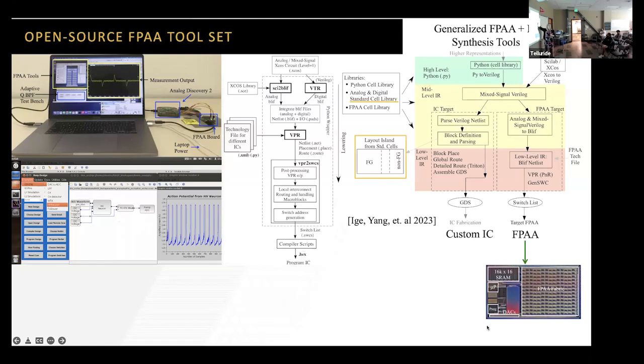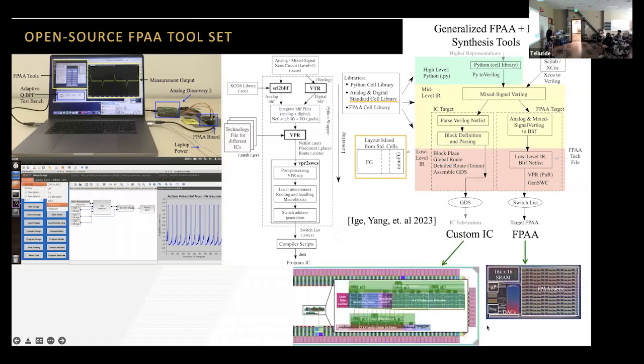You might also go, wait a minute, there's a different side to this flow that I forgot to tell you. I have a mixed signal structure from this high level. Same concept, that could go down into this side of the FPAA, but can also go here, and now I can have a whole flow that takes some Verilog, taking a whole set of standard cells from the analog side as well, and come down towards a custom IC, which is actually the 65 nanometer one, so I can take this as standard cells and run it straight down. This is some of what we're now starting to build a lot with, building standard cell elements to take this high level description all the way down. It's also a nice idea that if I want to make the next generation of these, I can start compiling those too, really leveraging the tool framework. So much of that came from understanding as we started to build this.